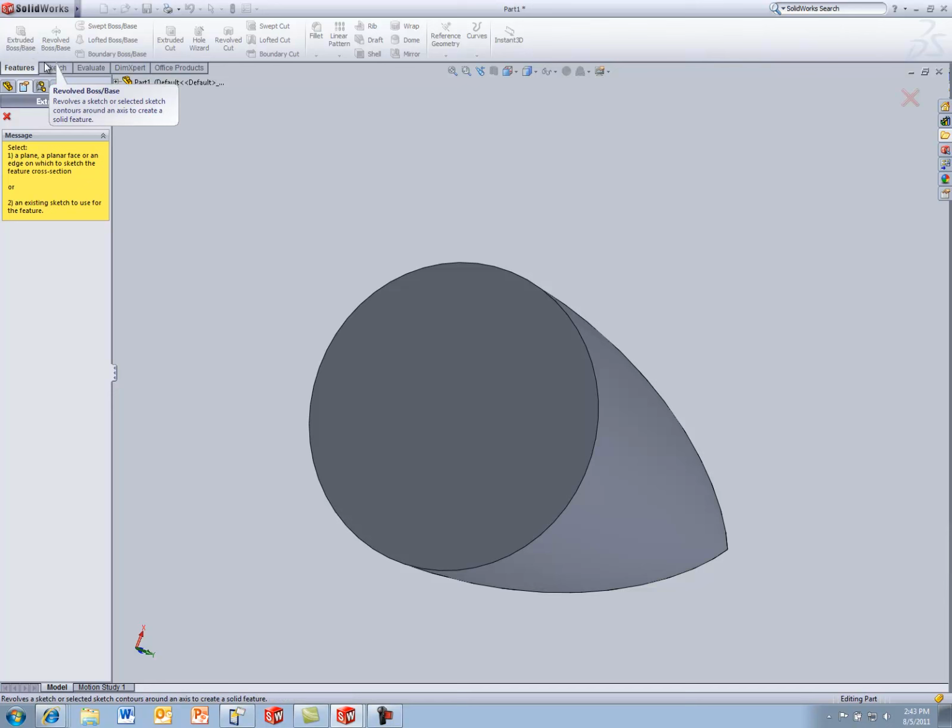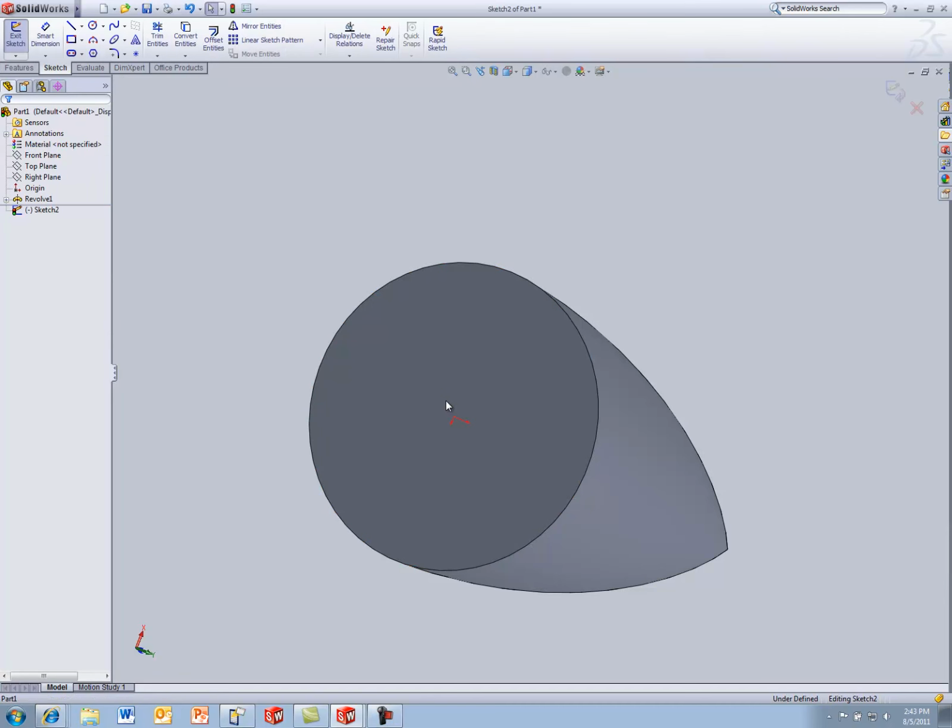Now we're going to draw the body tube of the rocket. So once we do that, we'll be prompted to select a surface. We're going to move our pointer to the existing circle. And you can see the perimeter will change color once we do that. We're going to click once to select this surface.